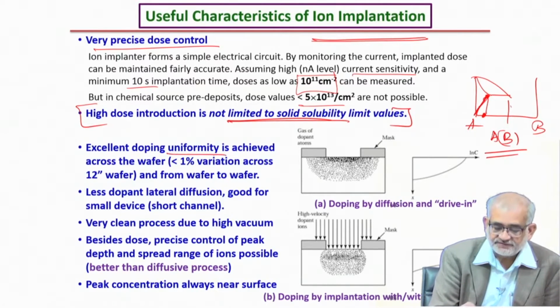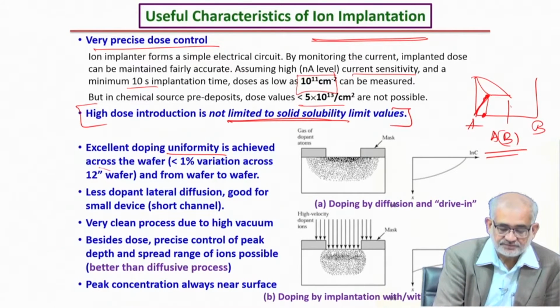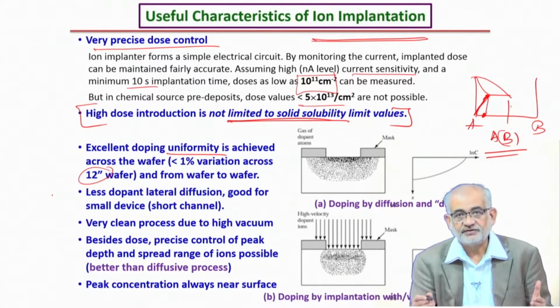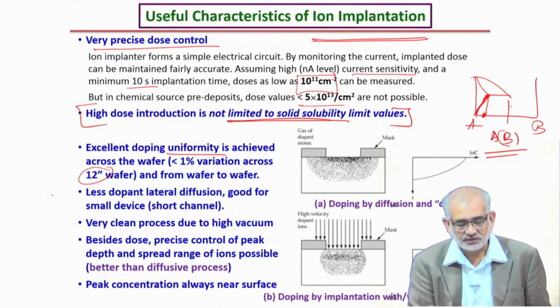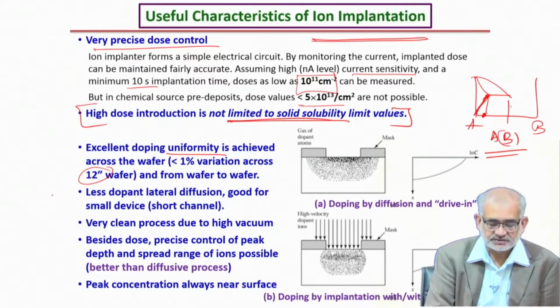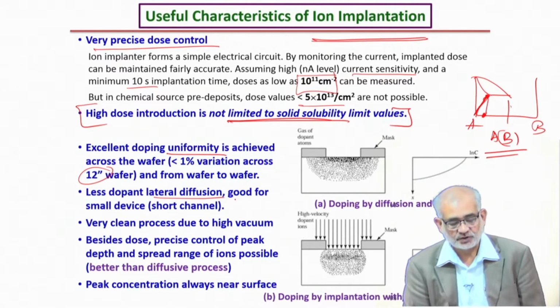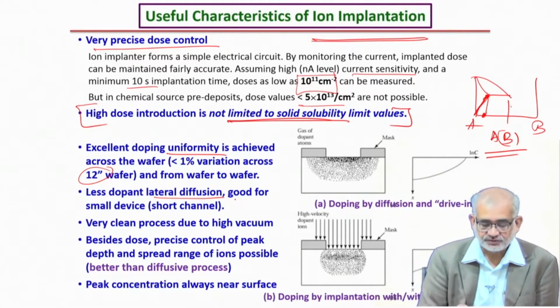I also can achieve fairly uniform doping. So for example, even a 1 foot diameter wafer can be implanted with the same concentration of ions throughout, I mean such a precise control. The dopant diffusion along the lateral direction is small, and that's really of advantage to us.